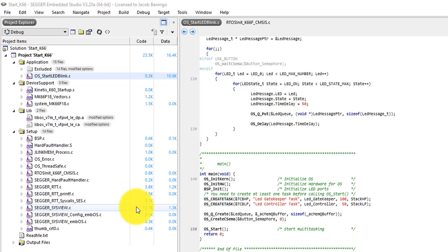Now, as it turns out, RTT is actually extraordinarily fast. It can transmit data in microseconds or less. So this has very little overhead in our application code. And when we perform real-time trace, we'll actually see that in the timestamps as we look through that a lot of our application is going to be idle and that there really isn't any effect from these libraries communicating the trace data back up to our application code.